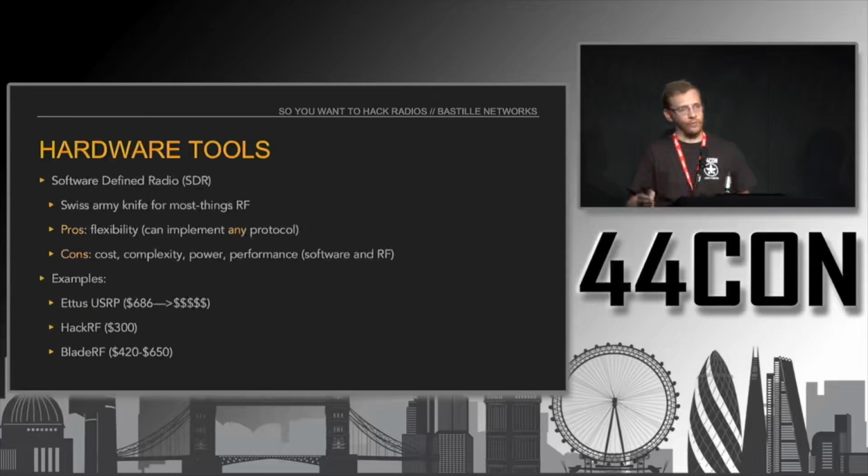We then have software-defined radios, which are a flexible RF front-end. So this is a radio you can tune to different sets of frequencies, set to different channel bandwidths, and all this raw radio data gets piped to your host computer. So instead of having the logic baked into silicon, the logic that speaks each individual protocol is then implemented in an FPGA or in software. And this is really, really great for doing research and reverse engineering because it's possible to iterate quickly. Instead of making a hardware change to tweak the protocol, it's just a tweak in software.